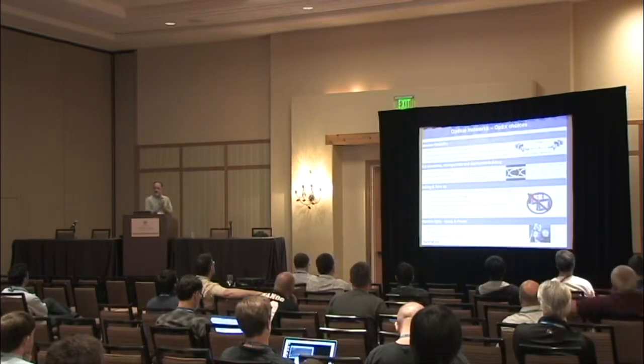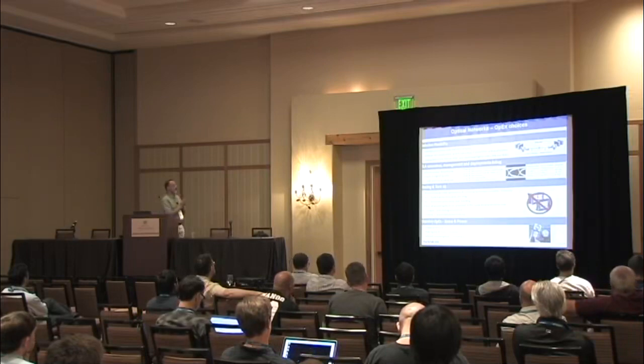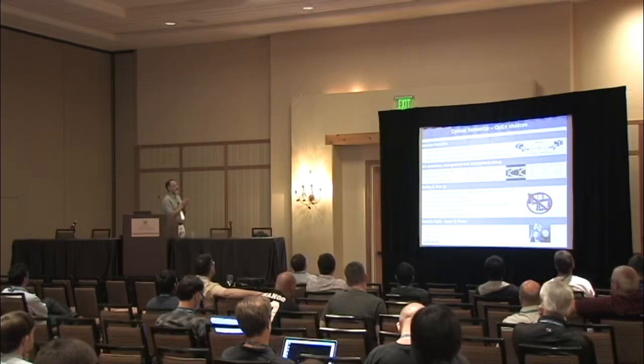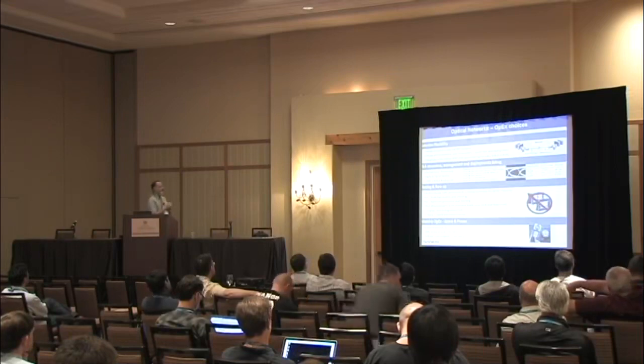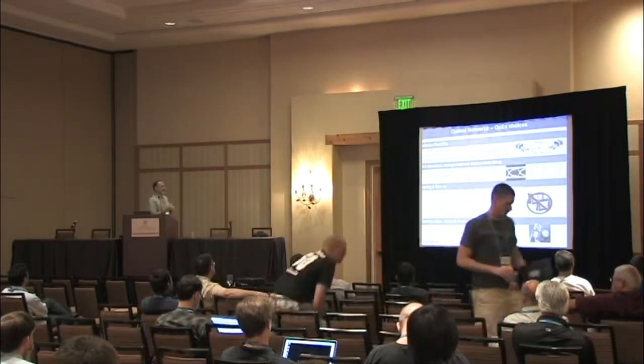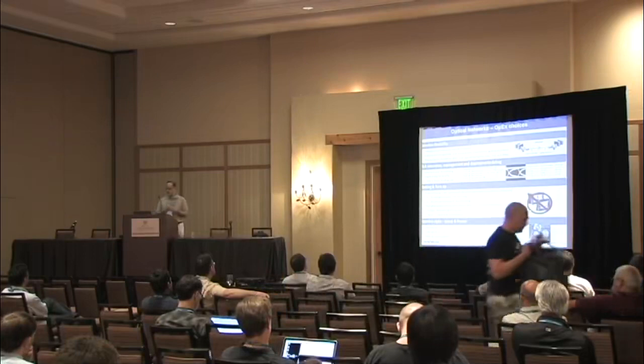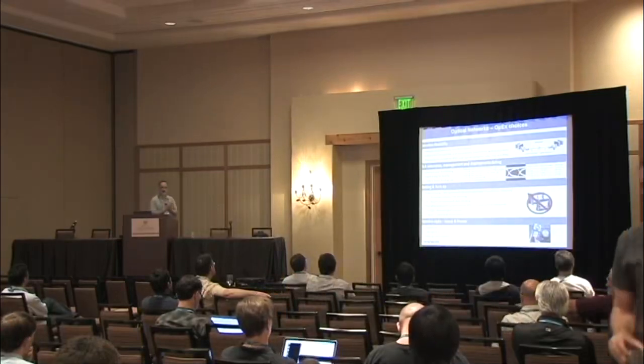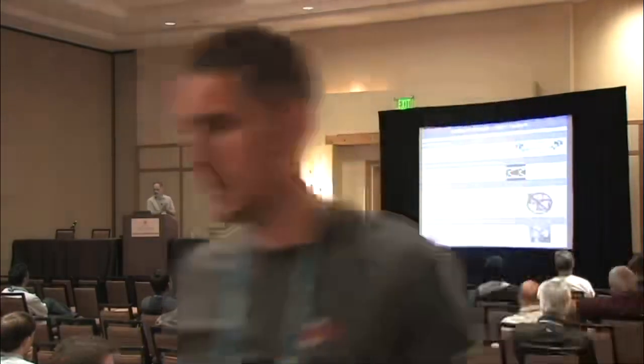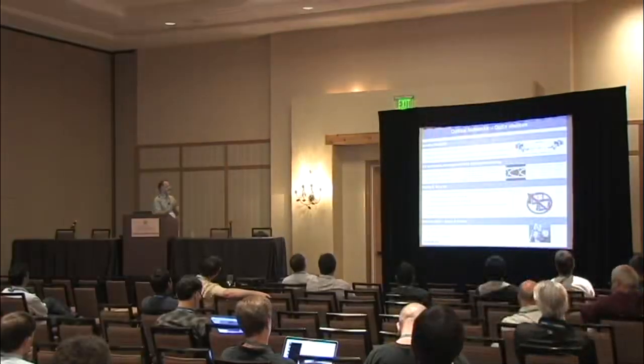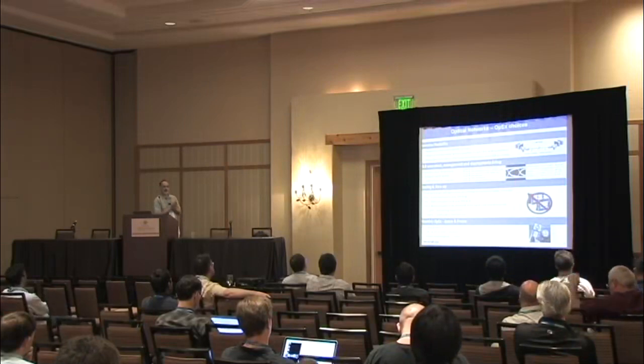Finalizing, going back to the simplicity. When you look at do-it-yourself of this type of networks, look at the capability to implement from the simplest to the highest, from media conversion to DWDM. It's interesting to have the same elements doing both converters and multiplexers and transponders and muxponders, not different tasks. Look for adaptability from 10 gig to 100 gig and look into the future. 200 gig and 400 gig are probably a few years away.